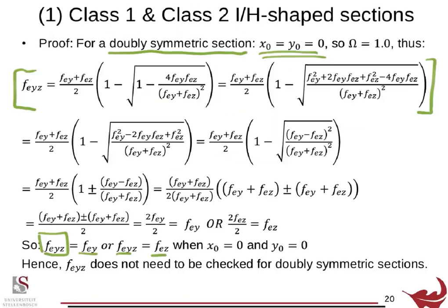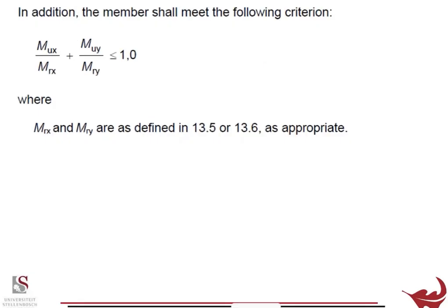Once we've done those 3 checks, then we move on to biaxial bending, or just a bending check. And then even for uniaxial bending, you do this check. All you're checking is that if the axial force is really, really low, this basically just becomes a beam.